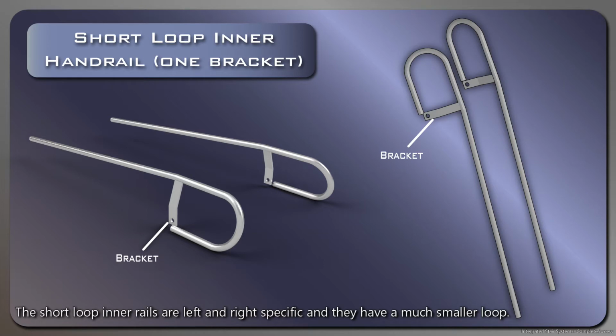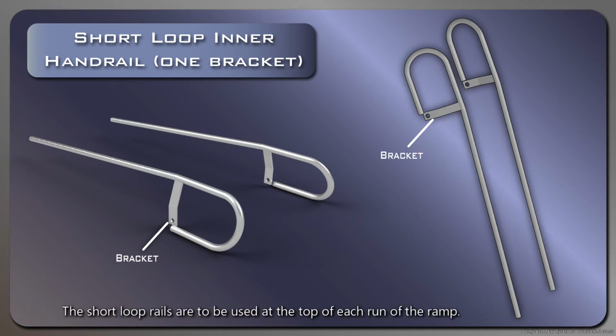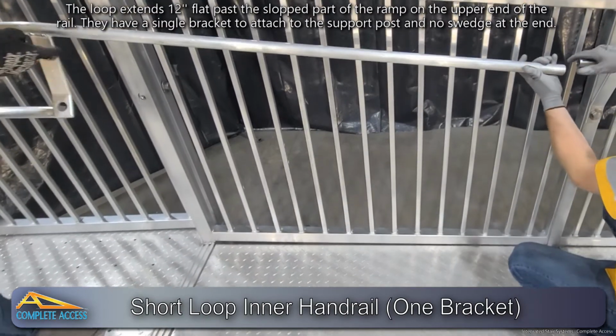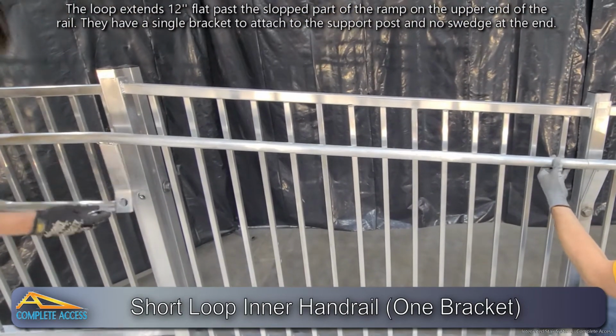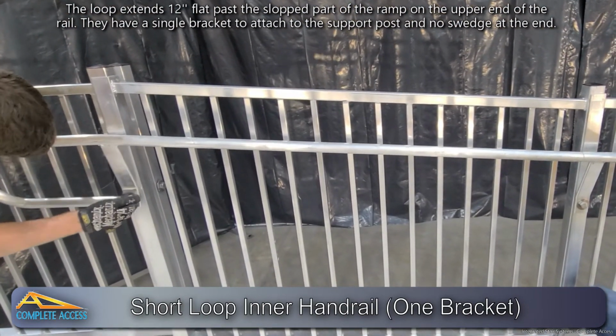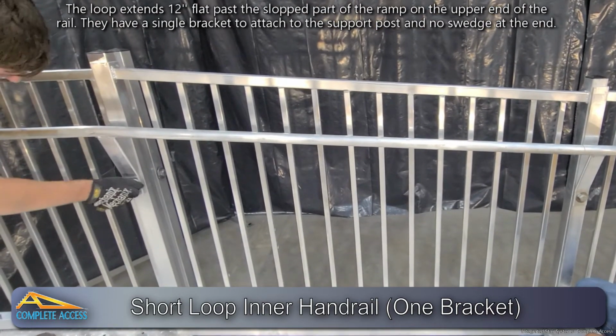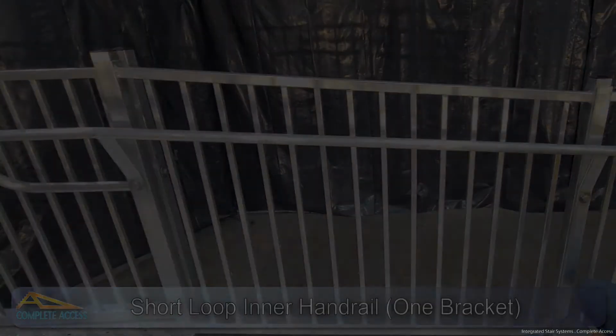The short loop inner rails are left and right specific, and they have a much smaller loop. The short loop rails are used at the top of each run of the ramp system. The loop extends 12 inches on level past the slope part of the ramp on the upper end of the rail. They have a single bracket to attach to the support post and no swedge at the end opposite the loop.